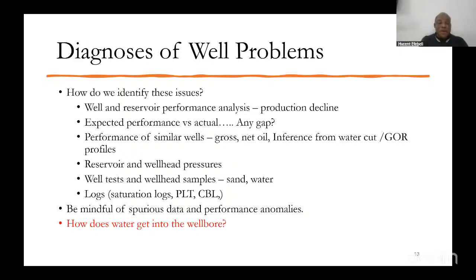Be mindful of spurious data, right? Some measurements may not be correct. So don't just take every measurement that you see, especially when it comes to things like GOR. Be careful, because GOR can rise very high, maybe because there was a significant reduction in net production of oil, right? So be careful.